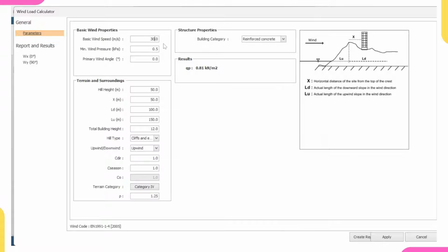average. Yes, don't go beyond, don't be doing the last 20 years or the last 30 years, because once it comes to the last 30 years, maybe that time the number of buildings in that area is few. That means the wind speed then will be very high. But maybe recently the development has started entering that area, so that means there are more buildings now. Those buildings will be restricting the wind speed. So that's why you should just take between now and the last 5 years.